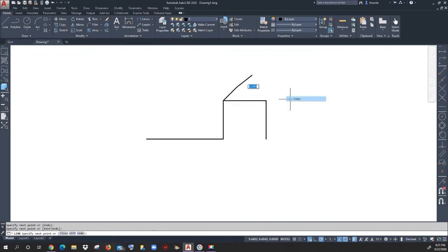So lots of helpful drawing aids with our toggle switches. We will always leave these on when we draw. There's a few occasions where I'll say turn your object snap off and place this and now turn your object snap back on, but you cannot draw properly unless you have your object snaps and your tracking, your polar on in your drawing.